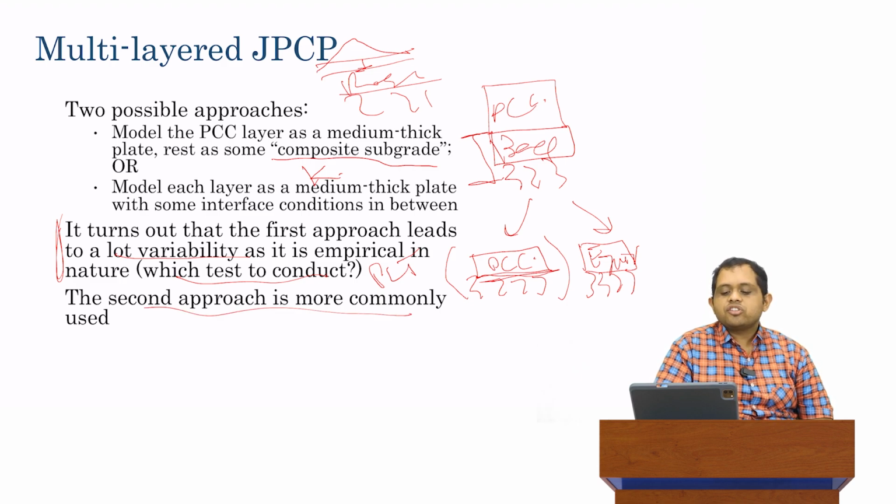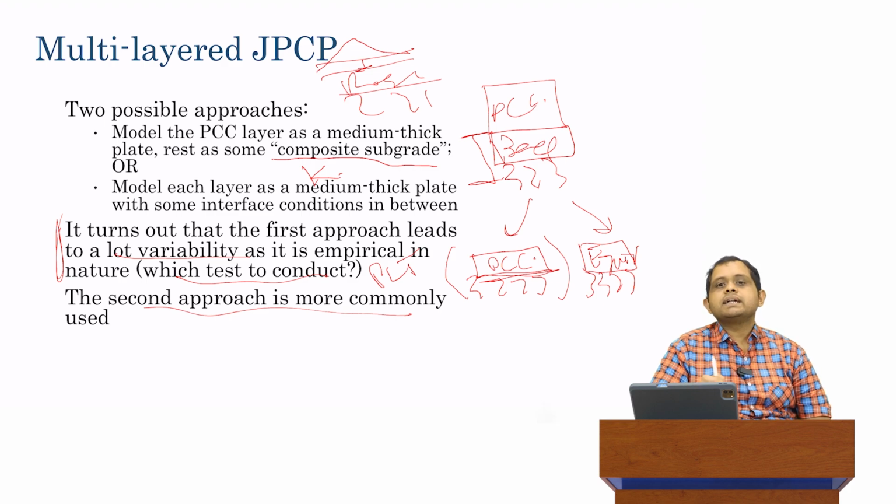The second approach, which is the equivalent plate approach, is actually what's used in practice. And therefore, in today's lecture, I'm going to take you through the equivalent plate approach. I again emphasize the equivalent plate approach, except for the approximation we have to make in terms of the interface condition, that we have to assume some kind of idealized interface condition. Except for that approximation, there is no other approximation which is made. The equivalent plate concept gives us exact values of stress, as though we were actually calculating it for two layers. No additional error is accumulated when we use the equivalent plate concept. That's an additional value of using the equivalent plate.